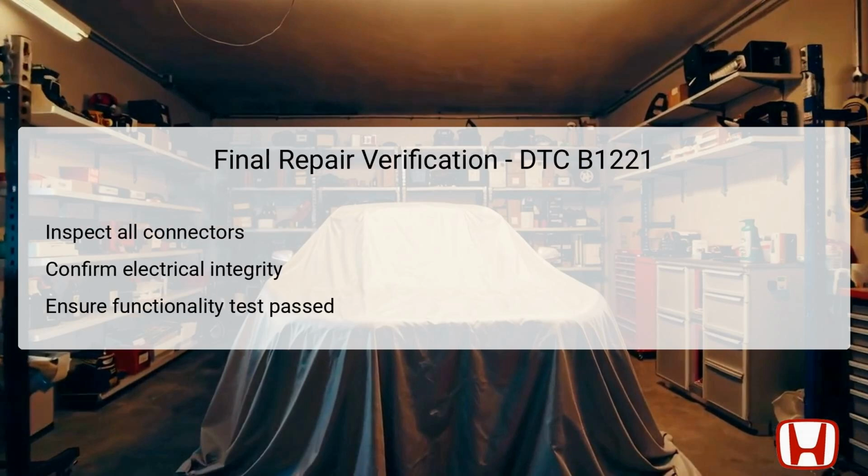After repairs are made, conduct a thorough inspection of all connectors and wiring involved in the rear mode control motor circuit. This ensures that all connections are secure and free from corrosion or damage. Verify the electrical integrity of the entire circuit using diagnostic tools, specifically focusing on continuity in the wires leading to both the rear mode control motor and the AC control unit.